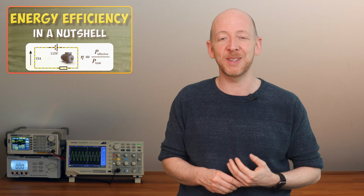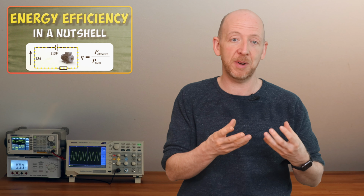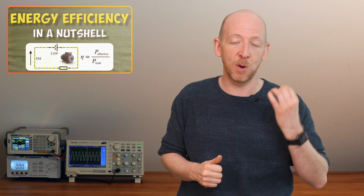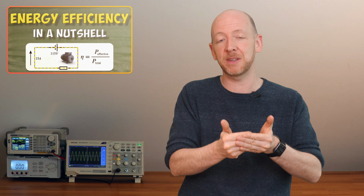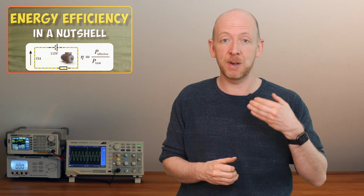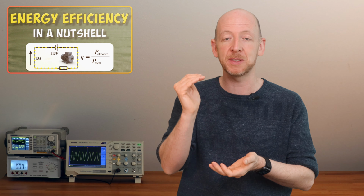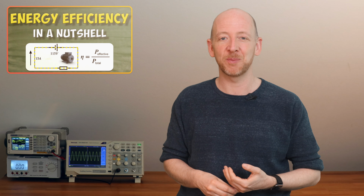On the bottom here you can see 3 devices to conclude this video. The efficiency of a light bulb is only at 5%, and you can also see the reason why these have been banned across Europe because of this really low efficiency, because 95% are converted into heat and only 5% are converted into light, which is what we want from a light bulb. Then you can see electric motors, which are above 90% in most cases, and also a solar cell, which is at only 12%, but since the energy is coming directly from the sun, we can live with a very low energy efficiency factor here.